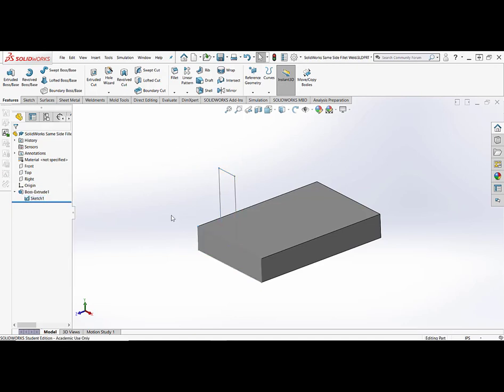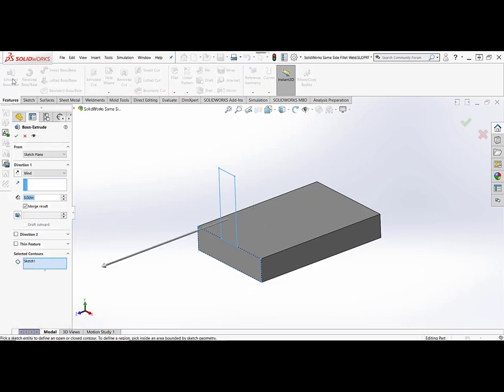So here we see that sketch. I want to make that sketch active. I'm going to click on it to highlight it. So now we see it's highlighted here. I'm going to do extrude again. And again, I'm going to drag this arrow back this way, and I'm going to tell it to go 3 inches. Now this next step is really critically important.